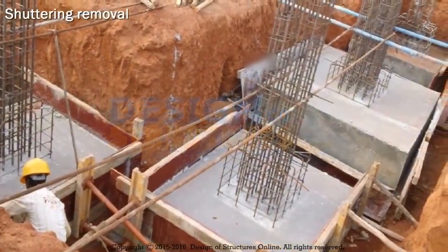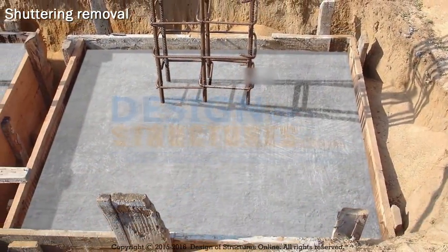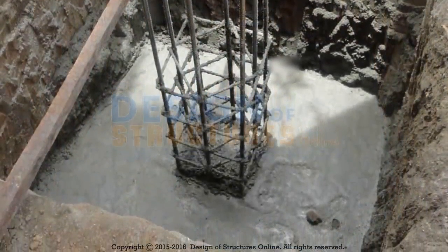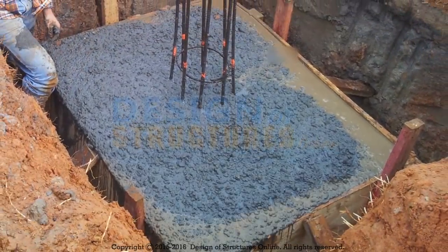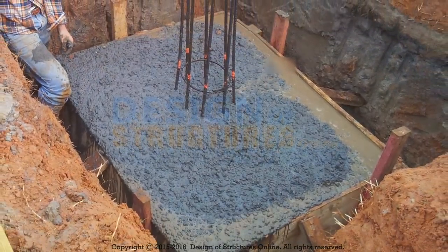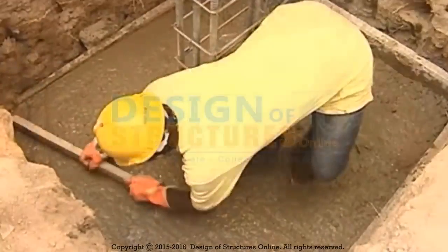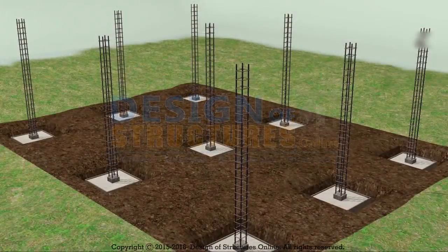Shuttering removal. The formwork removal procedure should be supervised by the engineer to ensure that the quality of hardened concrete and structural member is good. That is, it should be free from or have minimum casting defects such as honeycombing, size and shape defects, etc. These defects in concrete influence the strength and stability of the structure, thus immediate repair works can be done or the members can be rejected.